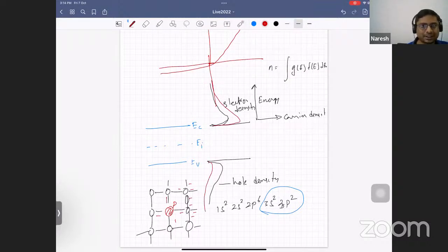And so we say that now the Fermi level is going to be where the probability of finding an electron is half. The energy level at which the probability of finding an electron is half. Now, since we are introducing electrons into the conduction band, the probability is going to shift towards the upper side. Correct? Do you agree that when I have an electron freely moving about, the carrier density increases in the conduction band?